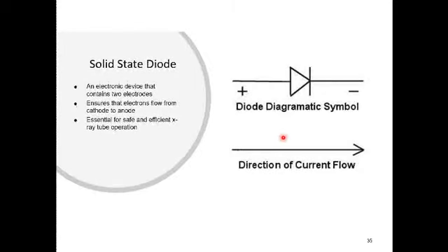Okay. Next. Those diodes that I pointed out in the rectification circuit, this is what a diode looks like. You've got your triangle here. And what you need to know as radiographers, it's very important, is that the current flows with the point and the electrons are going to flow against the point. So your negative section or your cathode section of your solid state semiconductor, your diode, which is your X-ray tube, your electrons are going to flow from cathode to anode, and your current is going to go from anode to cathode. Okay, super important.